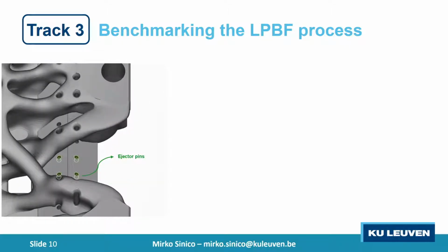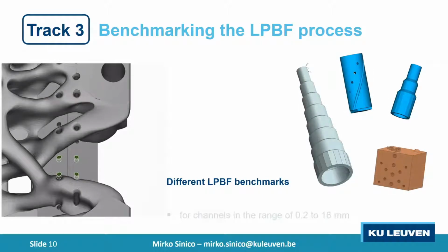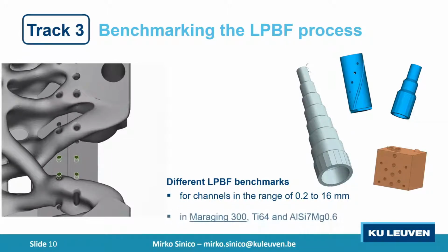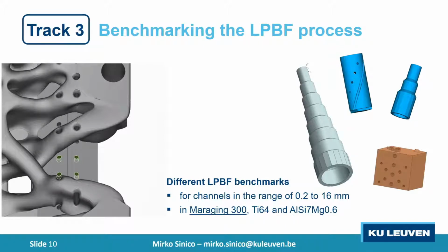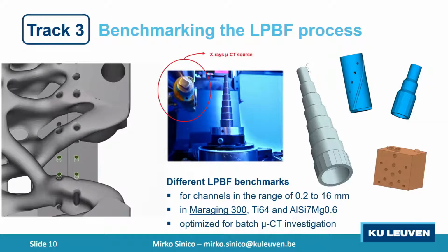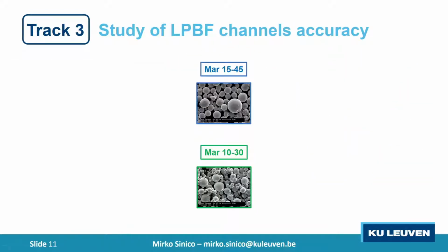For this reason, together with ESR 6 and 13, we derived LPBF benchmarks specifically for the investigation of channels in the range of 0.2 to 16 millimeters, produced in maraging 300 but also in Ti64 and aluminum alloy, and optimized for batch micro-CT investigation.